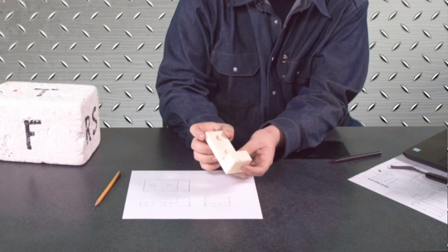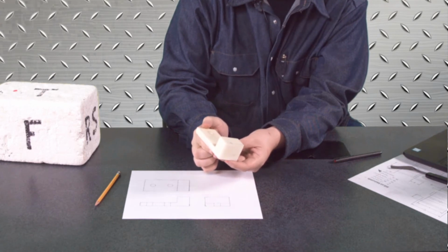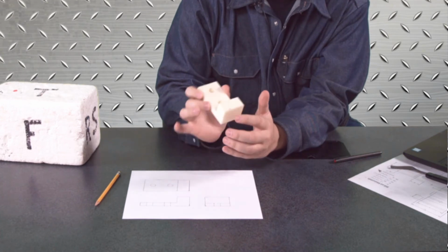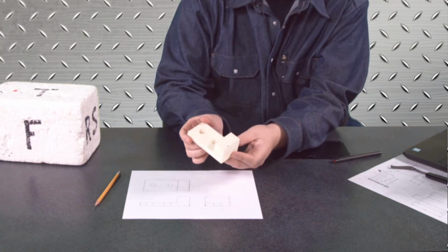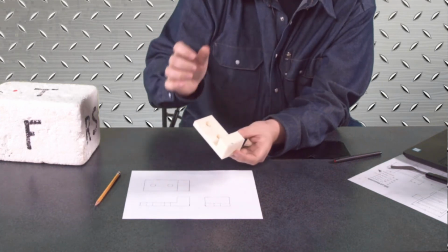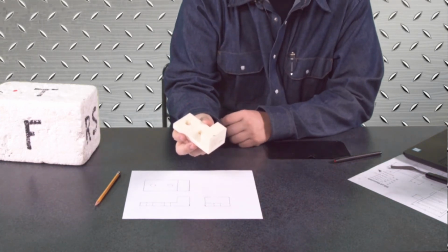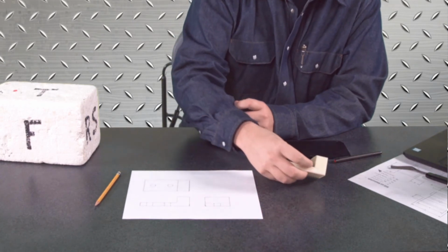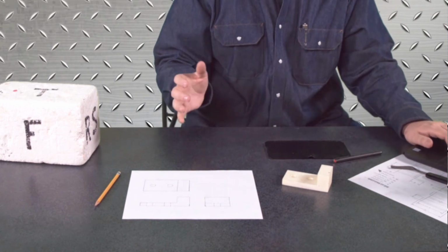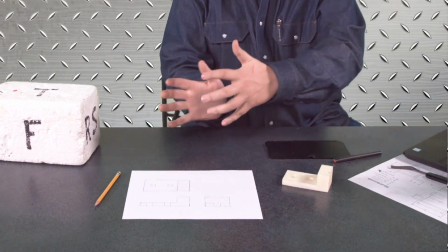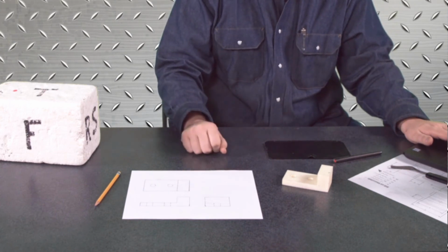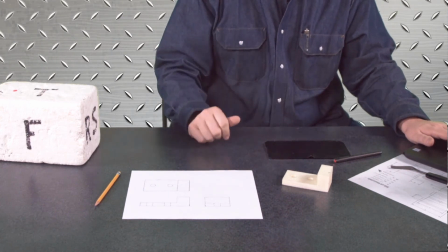Now the pictorial view you'll run into more often is an isometric view, mostly because it does not actually break the object or cause an optical illusion. Everything's set at a 30-degree angle. So you'll have your front side, your top side, and your right side view, and the object will be represented just like that. It's a lot easier to see in a three-dimensional space, in my opinion, than an oblique drawing, because the oblique actually warps the object and takes a plane and slides it off to the side. And of course, we have our orthographic projection, front, right, and top side view.